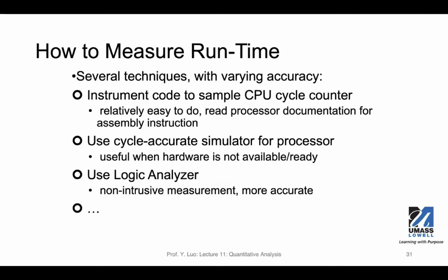The second way to measure the runtime is to use simulators. In this case, we need to have a cycle accurate simulator for a particular processor. And that's very useful if your hardware is not ready or available, especially for new products. This is the method that chip designers, manufacturers, and vendors have used for quite some time, including